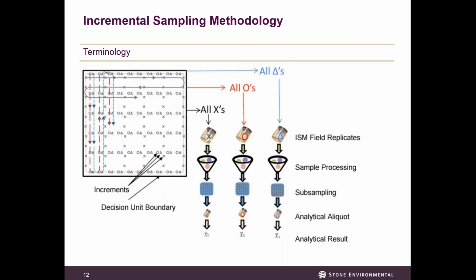Okay, so the soil goes in the pan. The pan gets mixed like crazy, and then you take a grid. You apply a grid to the pan, and you take samples from the pan using a flat tipped scoop of some sort to gain the entire thickness of the sample, because by shaking it and mixing it, you're going to get stratification of that soil in the pan. So depending on the density of the grains, it could be all the coarse stuff's at the bottom and all the fine stuff's at the top, or vice versa. So you want to make sure you collect all of it and weigh it out.